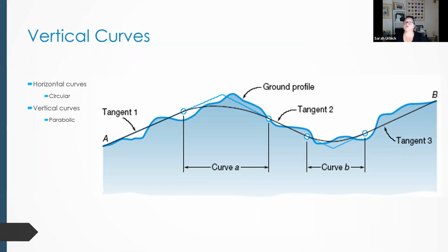that's what vertical curves need to be analyzed for. Can we get through there? Can we drive that? Is the slope too steep that a vehicle could not pull the grade? Okay. Depending on standard manufacturer's conditions.